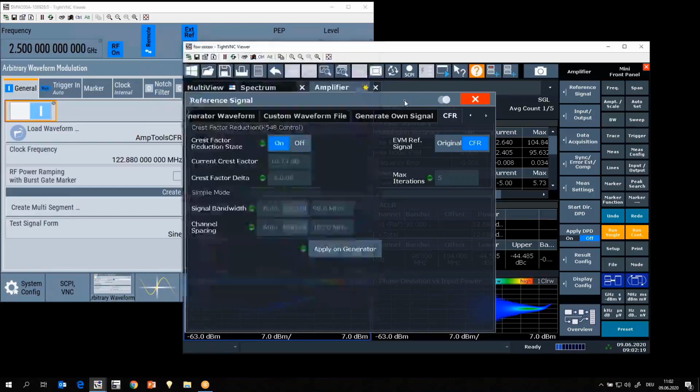And here is why. The next step in our process is that we want to run DPD. And when we run direct DPD, we don't want to compare the crest factor reduced signal to the original signal, because the result would simply be that K18 reverses the CFR mechanism. So internally in K18, for the DPD only, we use the CFR signal as the reference.